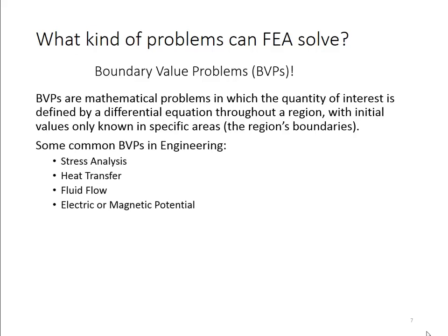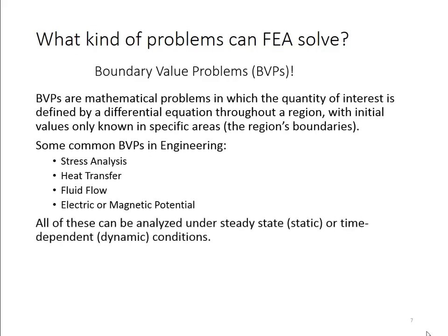Some common BVPs in engineering include stress analysis, where we are looking for displacements and stresses internally, but we know displacements and loads externally. Heat transfer, where we know temperature and heat flux on the surface, but we don't know what's going on internally. Or fluid flow, or electrical magnetic potential. All of these can also be considered to be a static or steady state problem, or a time-dependent or dynamic sort of problem.